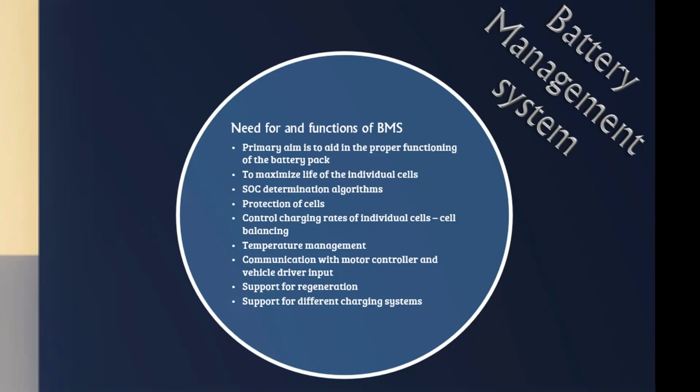So that is where the battery management system comes in, and it tries to maintain that uniformity by maintaining the charge levels on each of these individual cells.